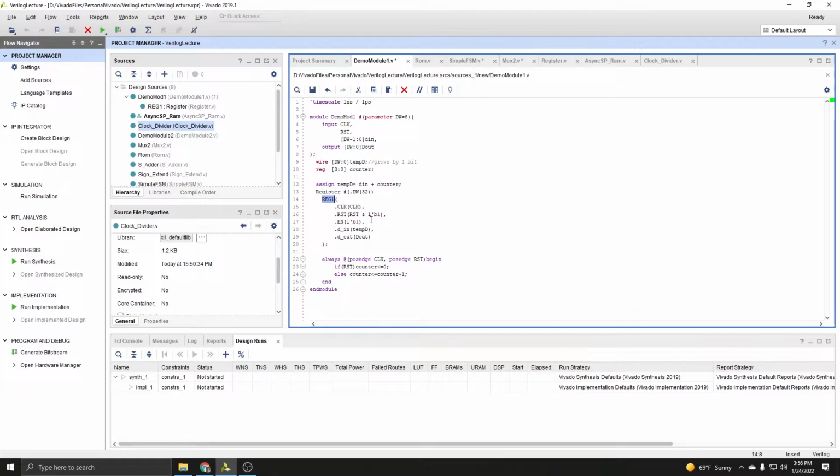especially things like the registers. I say just add the enable signal to your register, even if you're not going to need it. Even if you don't need to use an enable every time you use a register, you can do something that the book doesn't tell you, which you can already see here, is that you can actually use constant values as well as logical operations and various operators within your port declaration.